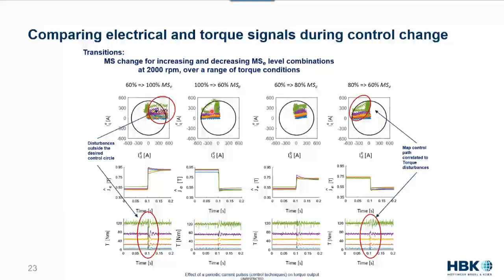When the operator sees the data go outside the black circle, they know that machine isn't operating the way they want it to, and whatever step caused that excursion from the black circle, they're going to say, we have to make sure our product doesn't operate in that way. Being able to record all of the currents and the voltages, calculate those ID/IQs, and look at everything in a correlated way really made it possible for them to analyze this data.